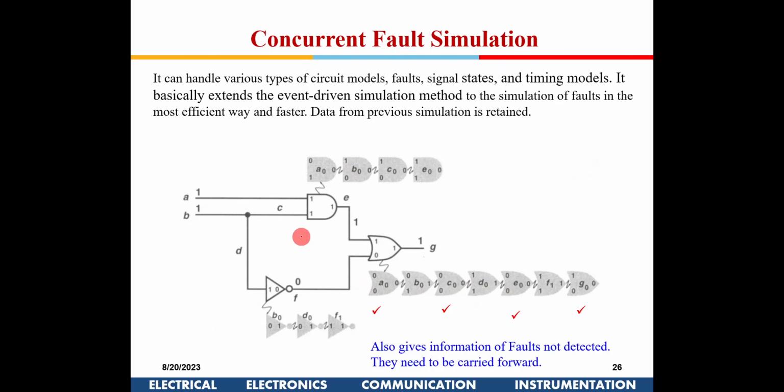So once we give the net list to the tool, in this particular case, the tool will generate the faulty gates for the net list which is being given, right? So this is not a universal gate list, it depends on the net list which we are giving to the tool. It will see, for these inputs, if this is the fault, is this gate affected? If it gets affected, what will be the equivalent fault gate? It will first compute all the fault gates for each of the gates in the circuit, and then it will start simulating them one by one.